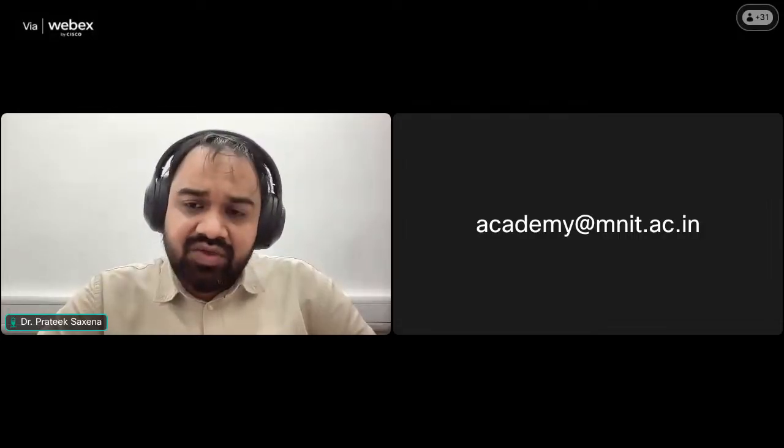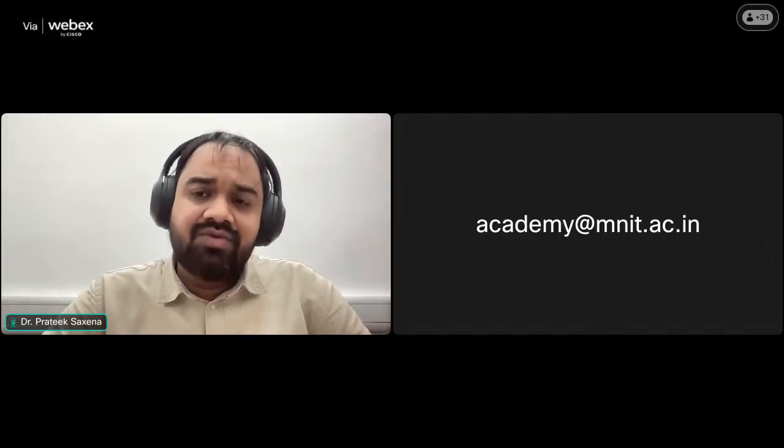So, Vishal, this depends. When you are making a filament, I have said wire, but it's basically a filament similar to a polymer filament. So whatever processing steps you take are in accordance with what you do for polymer processing. I think what you want to know is what temperature I should keep, because metal is also there. You don't have to worry about metal.